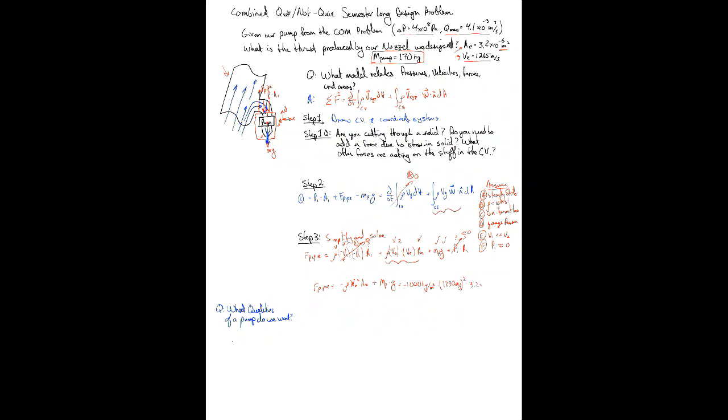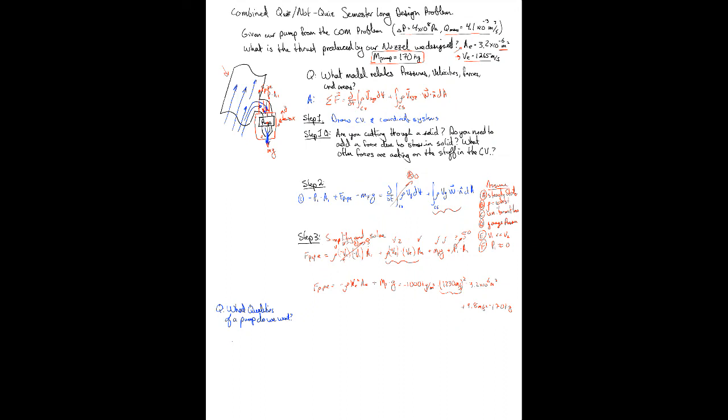So you can see that the thrust produced by our pump is equal to the density times the velocity squared times our area. So if we can increase our velocity, that's the best thing we can do, because any increase we get is squared, right? So that is excellent. And we subtract the weight of our pipe.